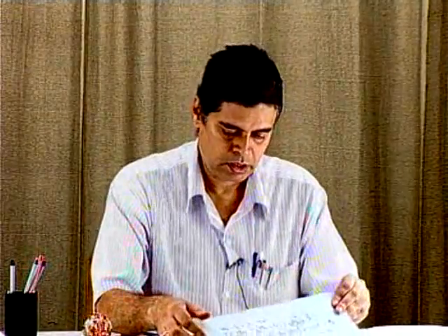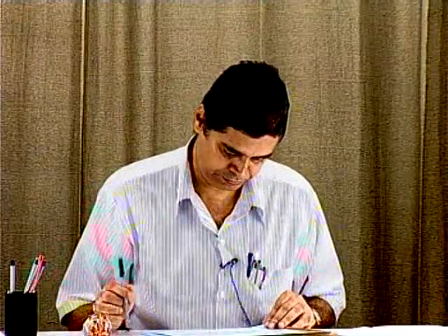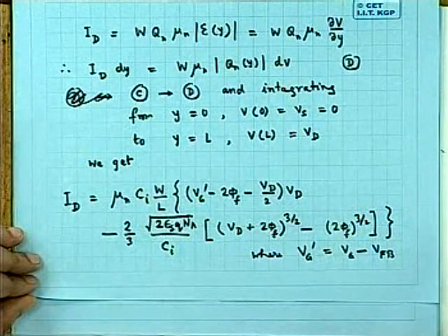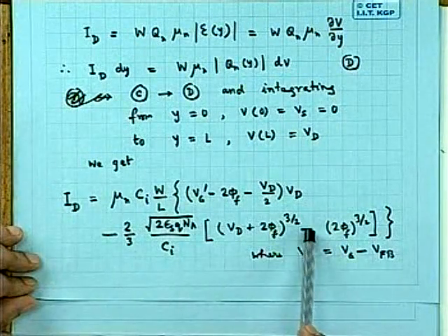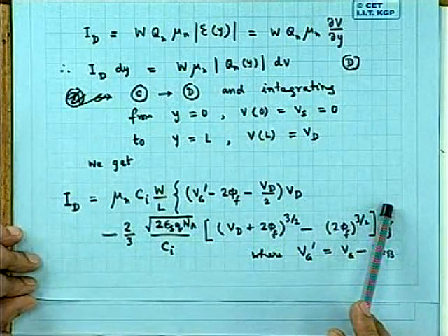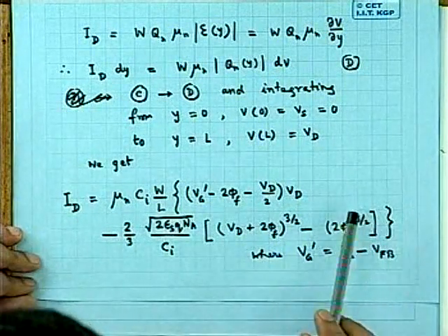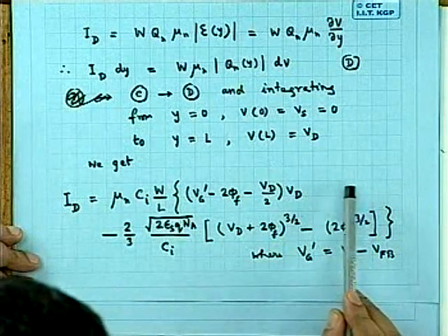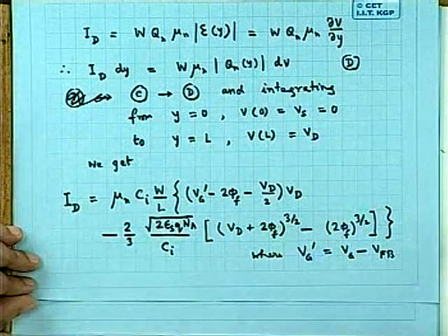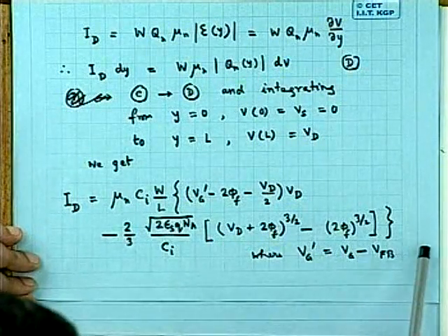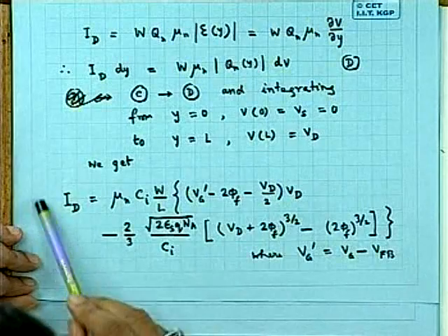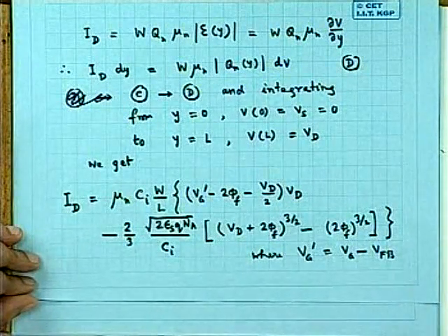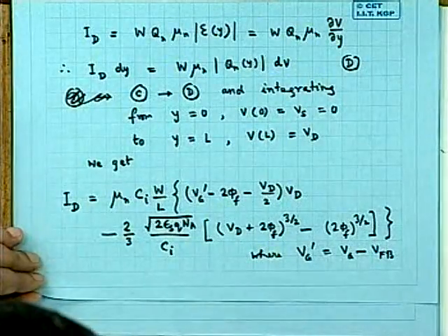Good morning. So we are starting today lecture 32. Remember, in the last lecture we derived this expression for the drain current. For deriving this equation we did not ignore the drain induced deep depletion, or the channel depletion. We assumed that the channel depletion is occurring also due to an additional potential induced by the drain bias, and that results in this expression of the current, which is more comprehensive than the simpler current equation derived earlier.